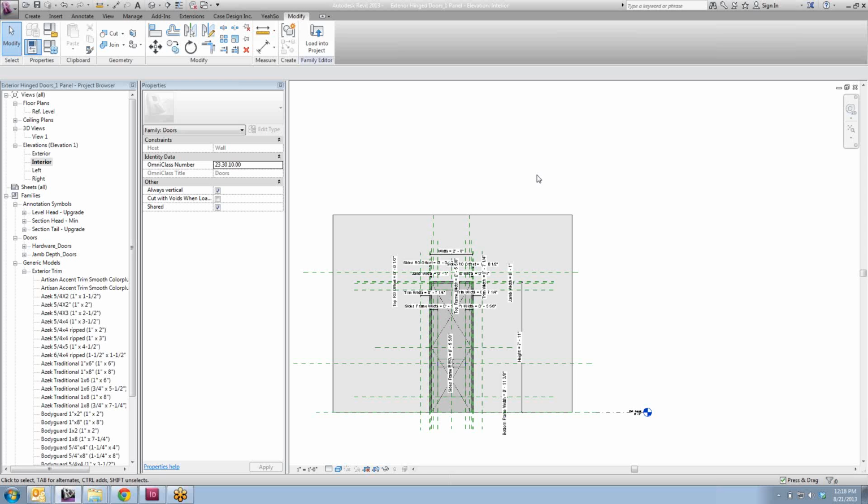Well, I'm not sure about the phase thing, but I know you can join them from separate phases, because there are times when you have a window and a wall that the window is in, which are set to separate phases, and they don't cut through properly. So I know you can join them, but it can be weird to do that. So yeah, we should look into that. Well, in my experience, if you join them and they're on different phases, the one that's on a different phase than the door isn't cut through properly. Right.